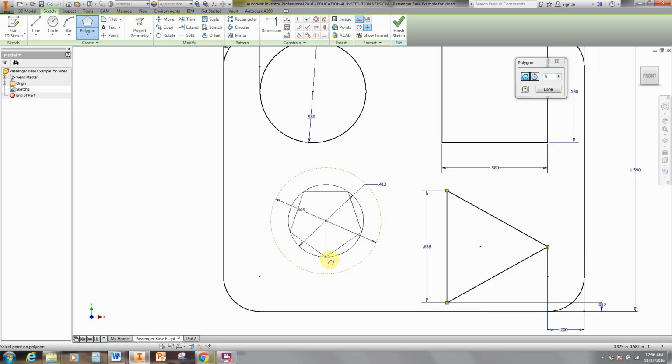So when we go down and hit that first circle, we can see it turn black. That's nice, but that's not where we want it. We want to touch the second circle. And you notice that directly above the cursor, there's a dotted line going to our center point. If I'm off to the right, or off to the left, I don't get the dotted line. But when I'm straight down, now I get the dotted line. That's very important. We need that point to be directly below the center point.